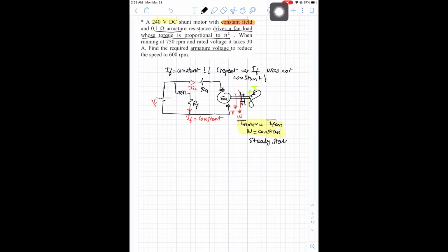the motor speed will be constant, and the motor will be running at constant speed. For the motor to run at constant speed, the difference between the torque coming from the motor and the torque coming from the load should be zero. There is no acting torque, or no driving force, so we don't have an acceleration.